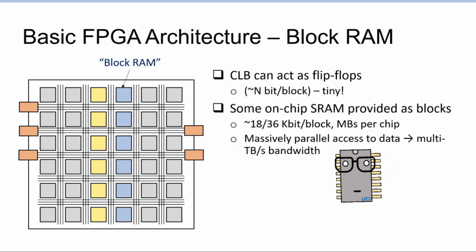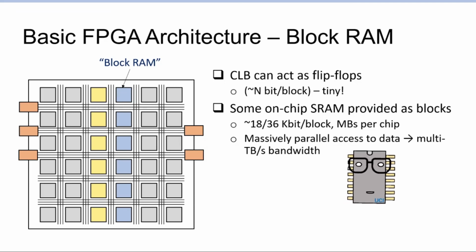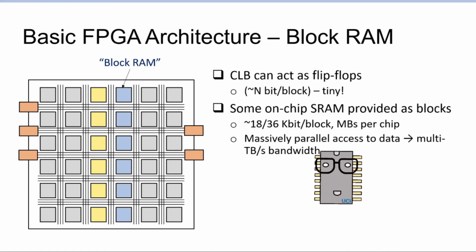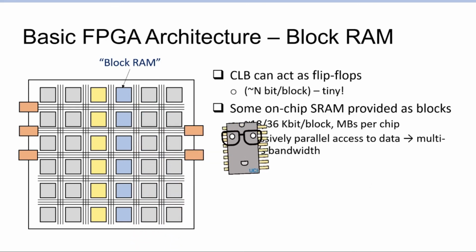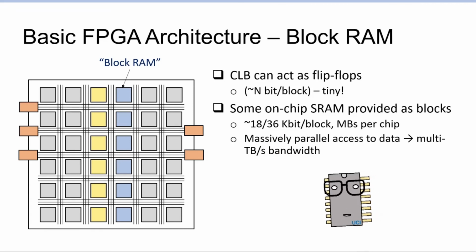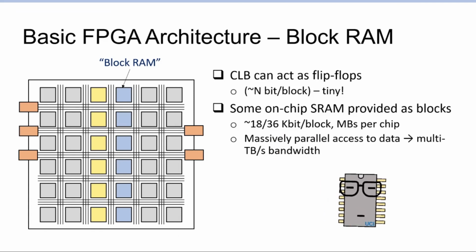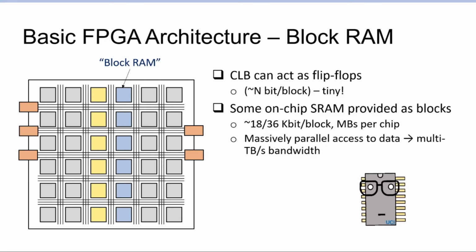And that's where a lot, and we'll get into more details about this when we actually get to the neural network portion of the ASIC design topics. But because a lot of applications are, and we've seen this already, memory bound, this is one of the big things that gives FPGAs the edge, because they can afford to provide memory in very, very small shard units instead of having a cache coherence or banks per core and things like that. If we just talk about the efficiency of bandwidth, this is a much more efficient way to organize memory.